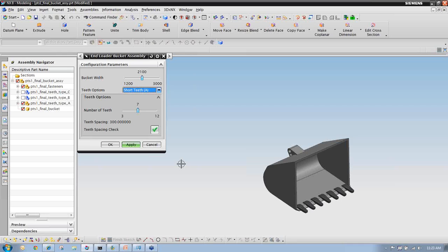This can be great when you have customer-driven changes where you have a conveyor that's so long. After it goes over a certain length, maybe it needs extra bracing, extra legs, extra rollers, extra supports. You can build all that intelligence in and also do error checking to make sure that it's manufacturable and it meets your true design intent, which is really what this comes down to.